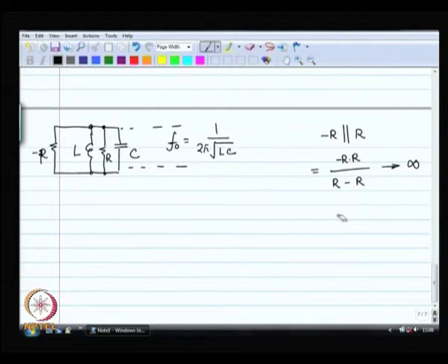An infinitely large resistance in shunt is as if you have got nothing in shunt, and in that case the system is going to start oscillating and the oscillations will be sustained, right. So, this is the thought that maybe I can invent a certain component which has an effective impedance of minus R, and I am going to put it in shunt with this tank.